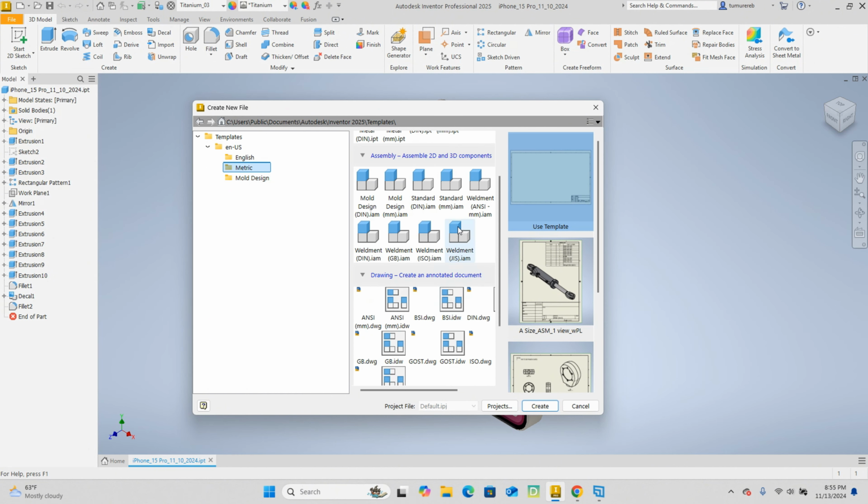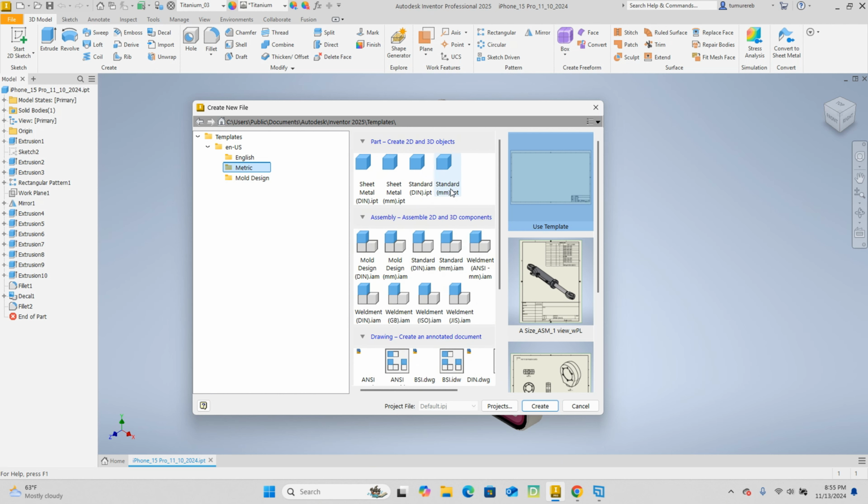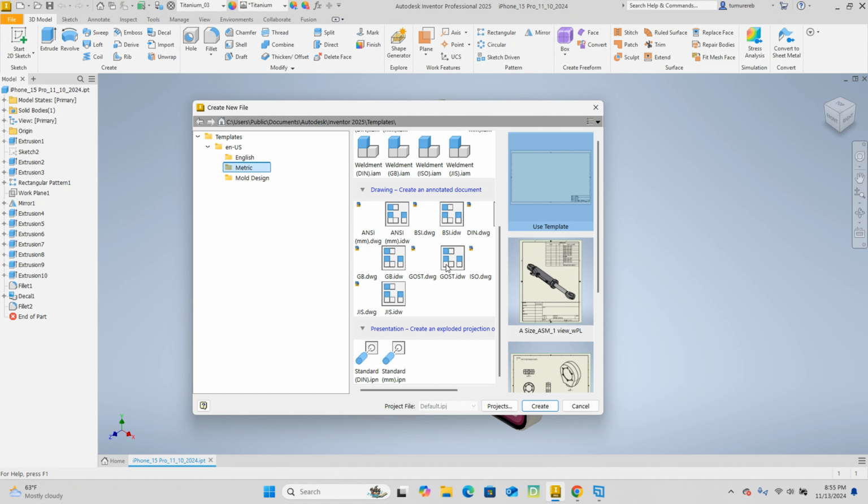These are the different Inventor file types. We are already familiar with IPT, that's for single parts. Assemblies, we haven't used much yet, but we're going to learn how to make assemblies. Presentation, we will learn how to do presentations. Presentation is when you create a video of your drawing. Usually it's better to do this when you have assemblies. And we are now looking at drawings.